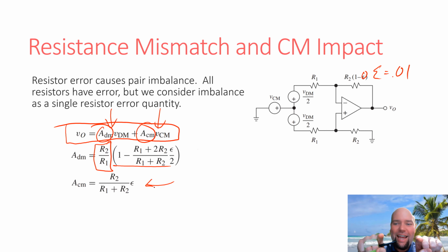What we mean is that if both signals go up and down the same, if both signals are fluctuating the same, the output should be fixed. We should only be amplifying the difference between the signals. We shouldn't be amplifying the commonality, which is why seeing the common mode in the output is bad. It's always bad. It's not ideal.